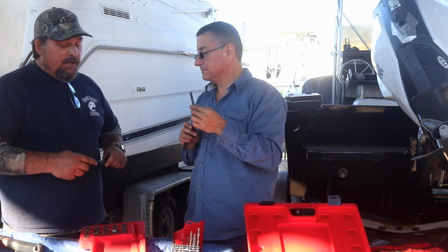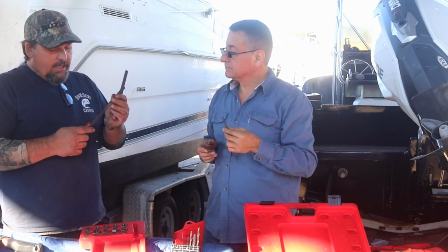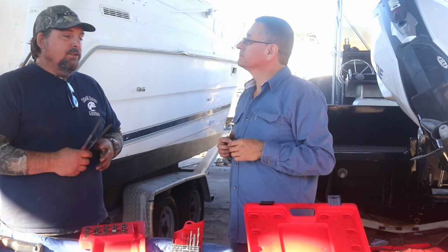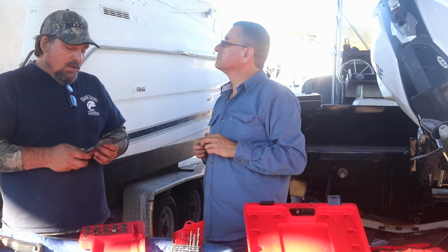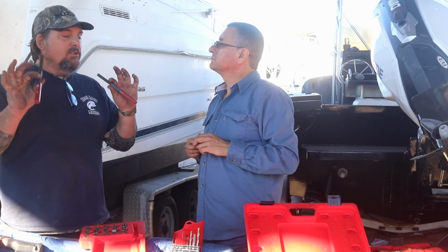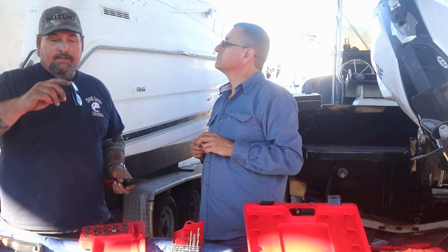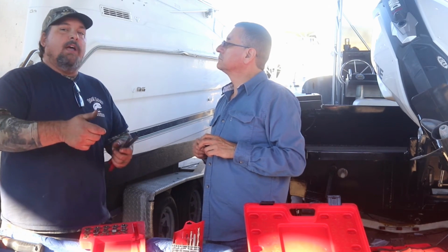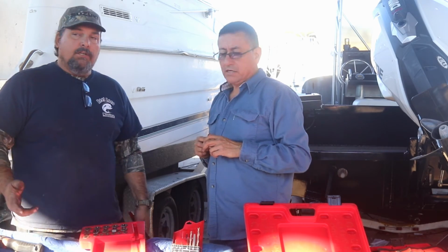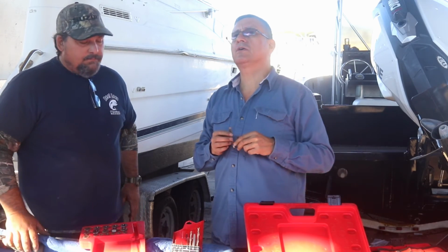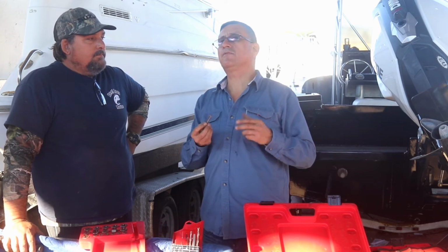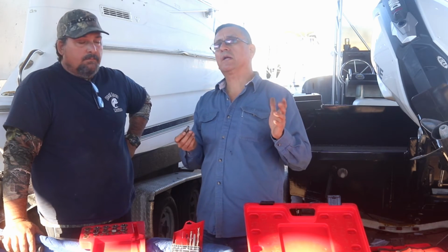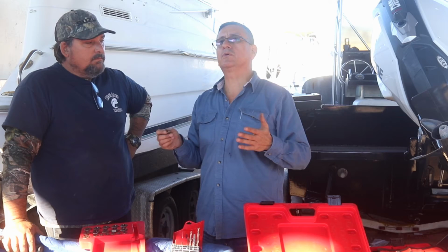And you know what's nice about these? You can carry them in your toolbox instead of carrying the whole entire thing. So if you're in the field and you damage the thread a little because you weren't paying attention, you could actually fix the threads with these. Listen, guys, if you're screwing in a bolt and it doesn't go, there's a problem. So you don't just keep going. You have to take it back out and check that the threads are correct. Correct. And in the lab, we are going to practice making threads in different types of metals, soft metal and hard metal. We are going to practice with a piece of aluminum, and we are going to practice with a piece of steel.